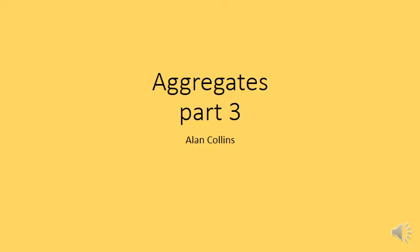And we talked about how, again, well graded and gap graded have a very low void content, so they can have more strength, whereas poorly graded, uniformly graded, has very low strength because it has a very high void content. Now, that doesn't mean we always want it well graded or gap graded, although we often do.